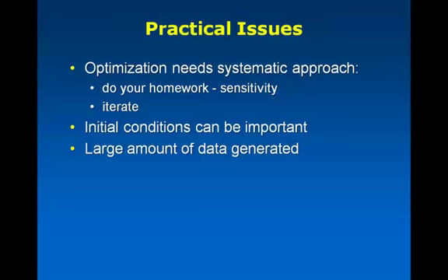So it's basically a few things that you need to keep in mind. You want to make sure that your initial conditions are good. So those are the first values that you've entered into the parameters that you're performing the optimization on. You have to make sure that the parameters that you're optimizing do have some sensitivity in the simulation. So if you're performing optimization on parameters that don't really affect the effluent that much, then obviously you're not going to have a very optimal situation.